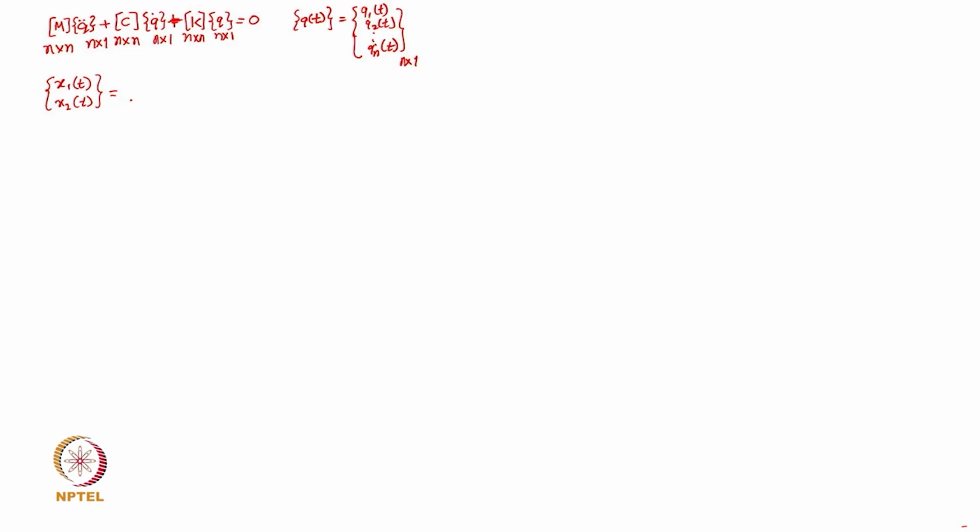all its modes. Okay. So, what I can write here is that this x1, the response of the first mass, is going to be written as some arbitrary constant a1 cos(p1 t minus phi 1), as we wrote for a 2 degree of freedom system, and the contribution from the second mode, which is b1 cos(p2 t minus phi 2).